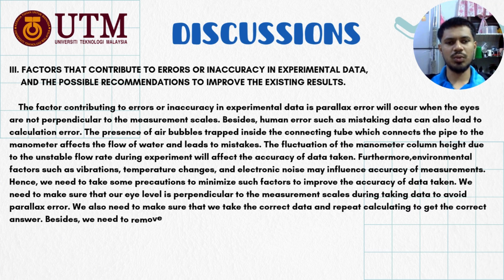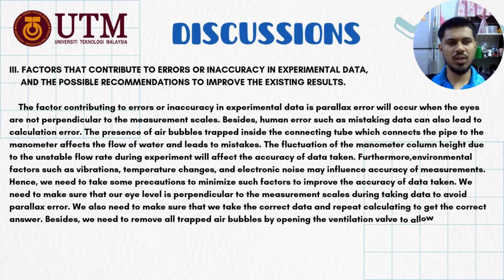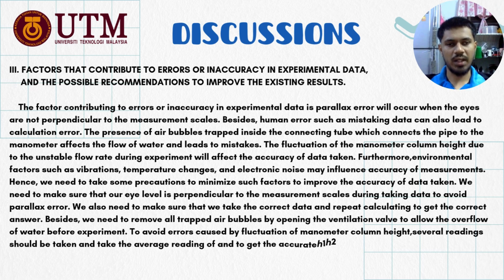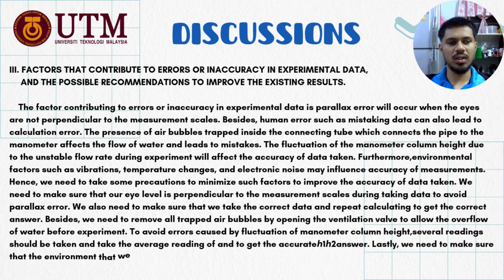We need to make sure that our eye level is perpendicular to the measurement scale when taking data to avoid parallax error. We also need to make sure that we take the correct data and repeat the calculation to get the correct answer. Besides, we need to remove all trapped air bubbles by opening the ventilation valve to allow the overflow of water before the experiment.